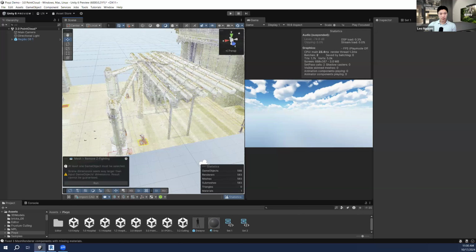Yeah. And it looks like I just pulled up the documentation page for supported file formats. So we do support PDF with Pixyz Plugin 3.0. It does not support metadata import, and it does require, from what I can tell, that it be a 3D PDF to import the data. It wouldn't be a workflow that I'm aware of to pull in a 2D flat PDF. It would probably go down that same pipeline that Leo was talking about with the SVG conversion or something comparable to a DWG.